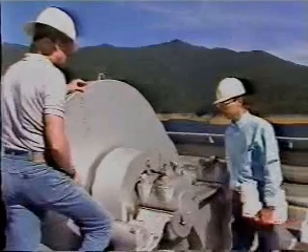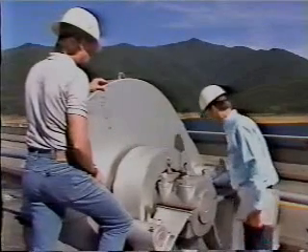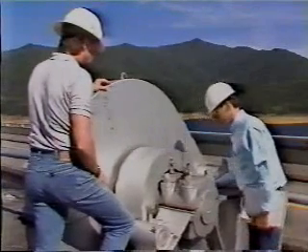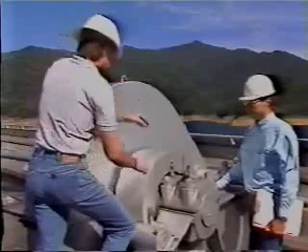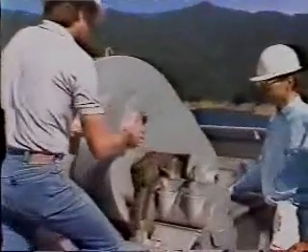Another thing to look for is surface damage. This includes corrosion, cracks, and loss of protective coatings. Also check for missing, broken, or loose parts, including damaged chains and hoist cables, missing bolts, faulty welds, and broken or cracked structural members.